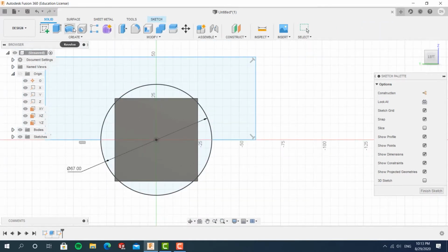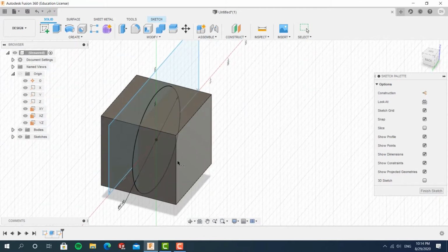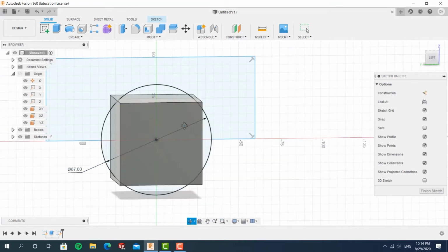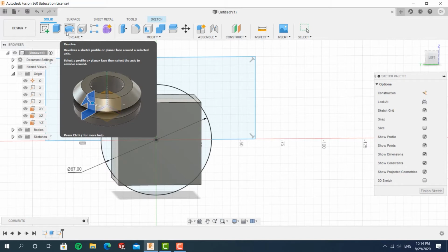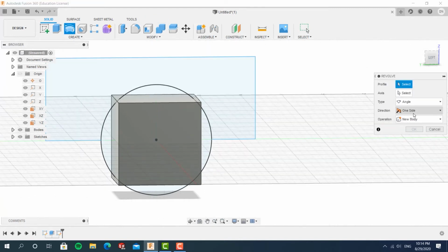Okay, so you just don't want to extrude cut the whole thing out, because if you extrude cut a cylinder out of here, you're just going to be left with these four awkward corners. You want to use a revolve cut. This function is basically just spinning an area around an axis after choosing to do whatever, either add a new body or cut things out.